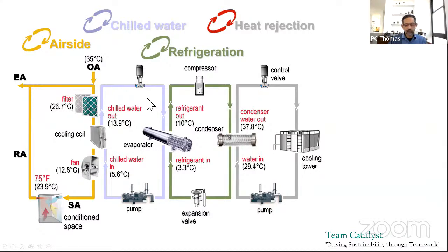So it makes cold water, chilled water, which you then use a pump to push through the cooling coil, and that makes the coil cold, the fan blows over it, and so on. And to make that chilled water, the chiller gets hot because it's removing heat from a cold space and it becomes warm. So the cooling tower, if you have a water-cooled system, tries to keep the chiller cool so it can do its job.